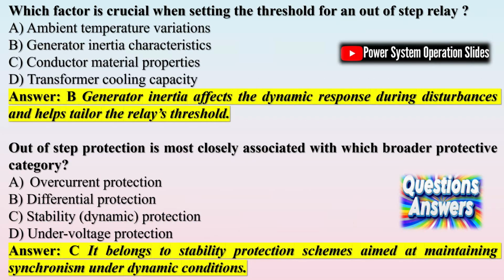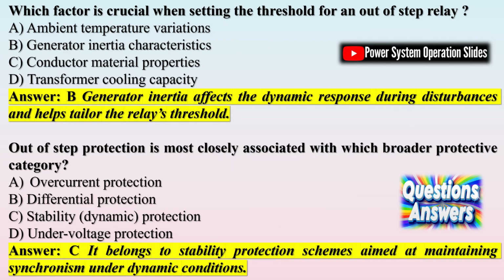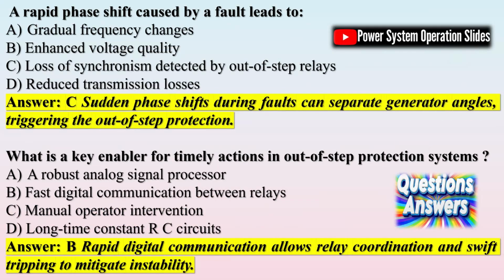Furthermore, the integration of advanced detection algorithms and dynamic relay settings enhances distance protection performance during complex system conditions, including the challenges posed by intermittent generation sources and rapidly changing load profiles. This detailed explanation touches on both the fundamental theory, like the power angle curve and transmission impedance during faults, and the practical innovations, adaptive tripping and blocking, PMU integration, that have advanced modern power system protection.